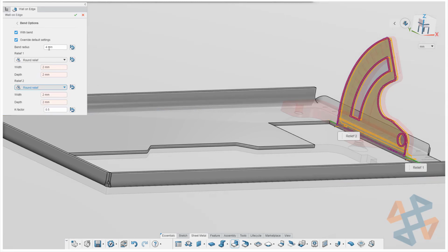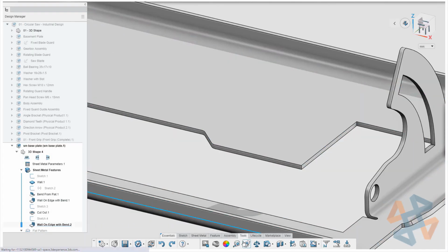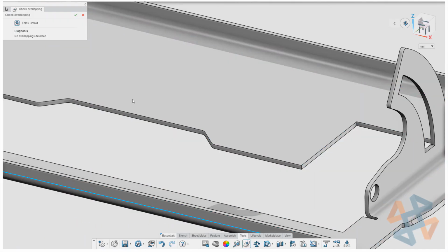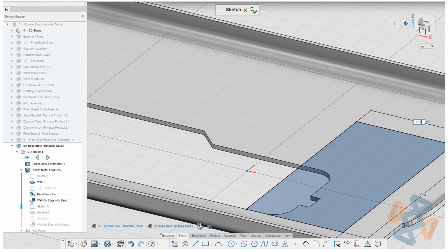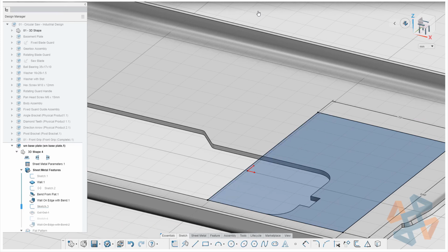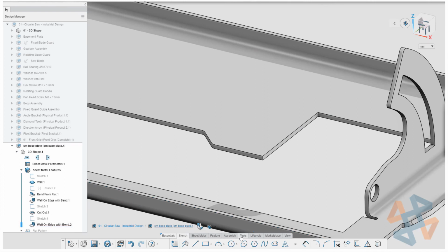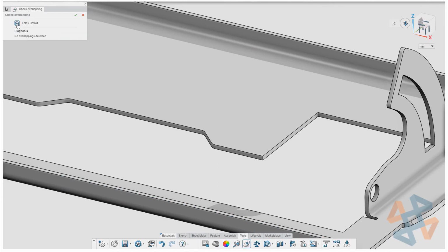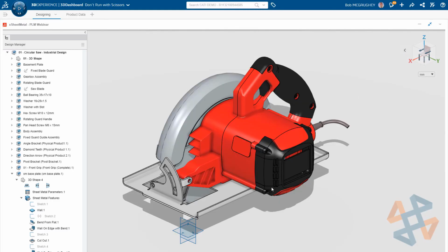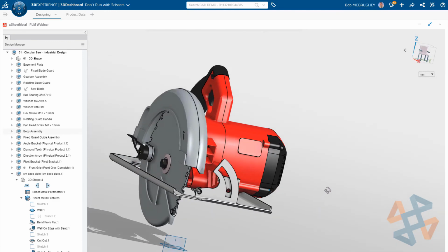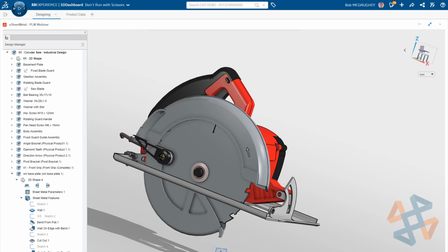Change the reliefs there so it fits in better. Maybe tighten the bend radius a little bit. And let's go ahead and do a check. We'll unfold the part and see if there's any interferences, which there is. So that flange does interfere with the part right there. Do a quick measurement. Looks like we got about 16.25 millimeters. So we'll extend out that cutout that we did by 20 millimeters. Do that check once again. Looks like we got plenty of clearance there. And now we've been able to substitute a nice sheet metal part very quickly, all inside of a web browser.